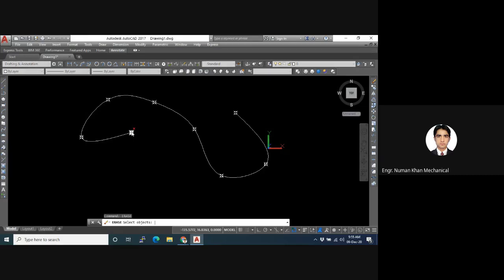This was done with a close fit, which means there was zero tolerance. By zero tolerance, we mean that we were not allowing the spline to deviate from these points which I have selected. Okay? But if I want to give it a tolerance, I can do it. When I select the first point, it has the option tolerance L. Why is L in capital? That's why we will type L. You can see the tolerance by default value was 0.